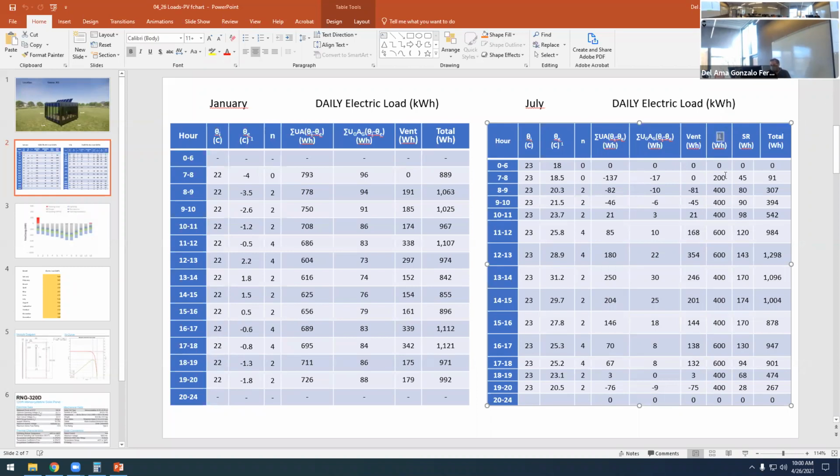Internal loads is about the people working in that building. If we have just 4 people, it's not going to be relevant. But if we had 100 people working in that building, or if we had a gym with fewer people, but all of them running or sweating or whatever, probably the internal loads will be more important.